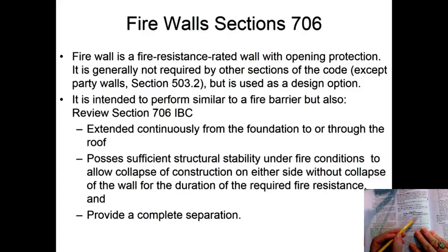It tells you what the ratings of those walls are. So if I have assembly, business, education, residence, whatever it's saying, you've got to have a 3-hour there. But it says, if it's a type 2 or 5 construction, the walls may be permitted to have a 2-hour fire resistant rating. So, of course, this is what it's talking about of your separation. So you've got to look at it.